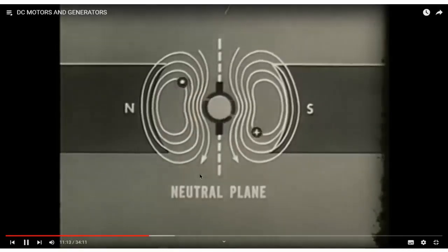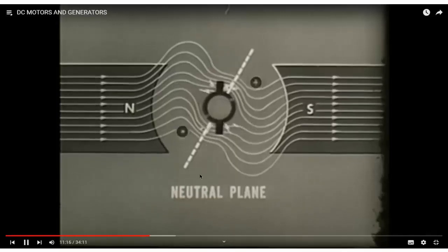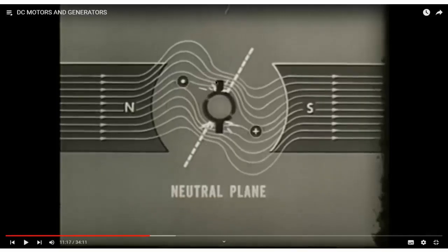This magnetic field interacts with the main magnetic field. Of course, those two magnetic fields will interact with each other and cause some distortion. Here you see, it distorts the field. And you see some sparkings, because the new magnetic neutral axis causes some realignment. It was vertical, but now it is diagonal.